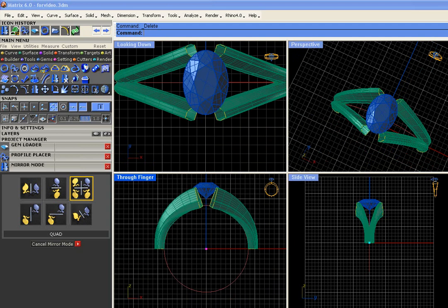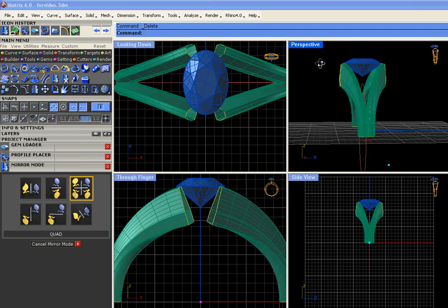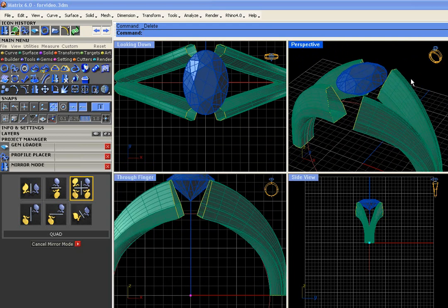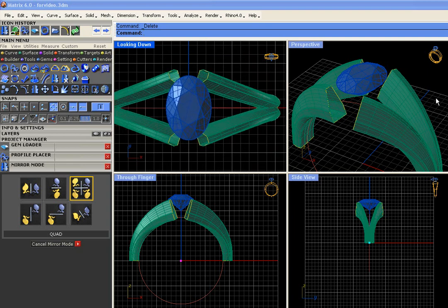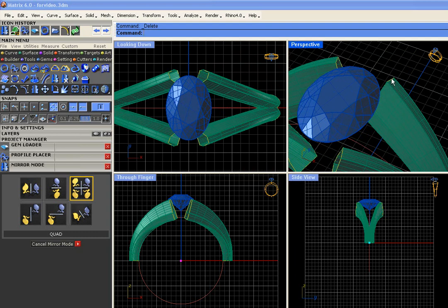But okay, now just take a look. What Profile Sweep is doing is actually using the blend tool, so kind of like your blend targets here, just without blend targets. So that's the only shape you're going to get. If you need to define this, go on to our advanced tutorials and look at how to use curve from two views with history and advanced custom rail. But if you just want a nice split shank design, practice profile sweep, which includes the history, of course. So when you move the profiles, the sweep keeps up.